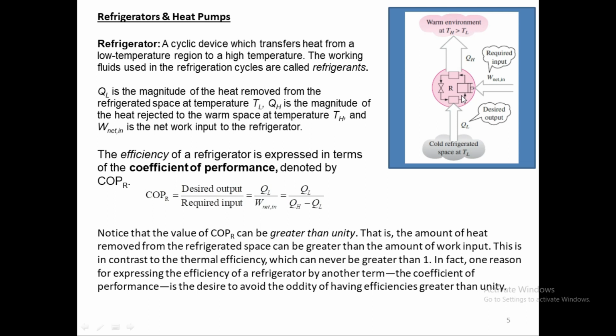So it's a two-phase system. We also call it a two pressure system, one high pressure, one low pressure. So high pressure is in the condenser and low pressure is in the evaporator. The pressure range in the condenser will be somewhere around 800 kilopascal to 1000 kilopascal, whereas in the evaporator it will be somewhere around 100 to 120 kilopascal. So as you can see, the evaporator is the low side pressure and the condenser is the high side pressure, and the difference is about 10 times.